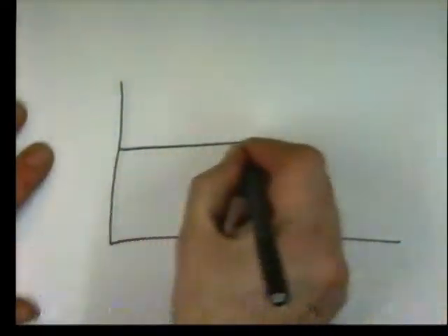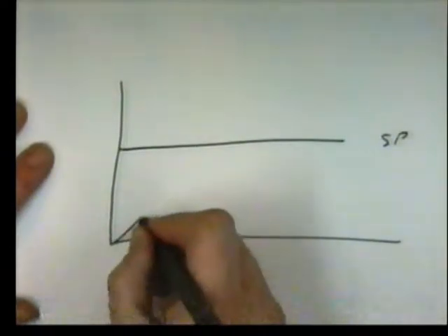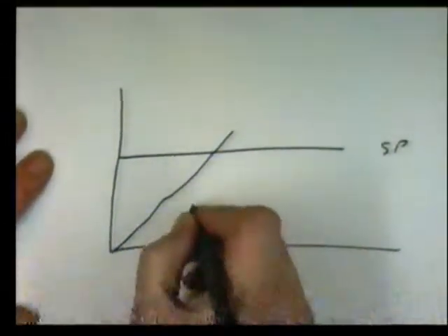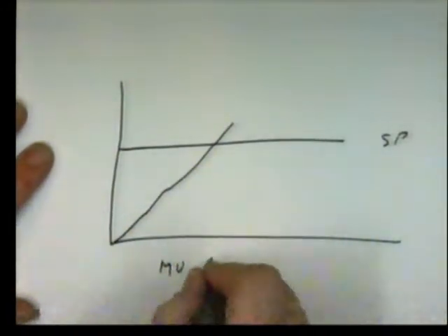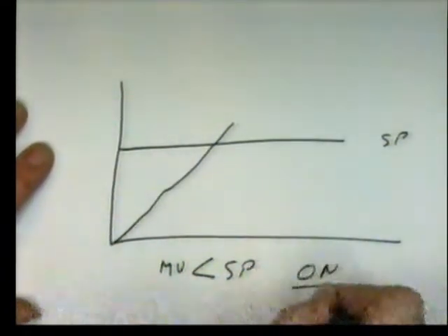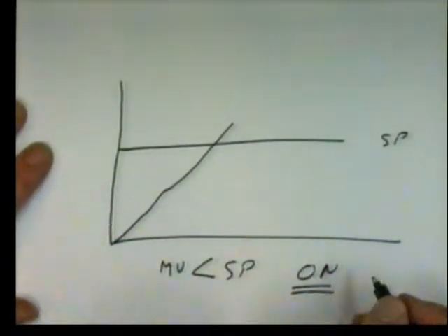If this is our set point, our measured variable will rise up till it reaches the set point, and it will always overshoot. So as long as the measured variable is less than the set point, the system is full on. There's no partial control, no gentle adjustment. It's either all on or all off. Just like air conditioning or central heating, it's just on or off.